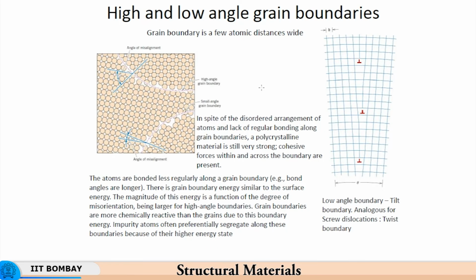The low angle grain boundary means that the two lattice orientations would have been the same if the misorientation had been absent. That slight misorientation is something that prevented the two lattice orientations from being identical, right? So the low angle grain boundaries indicate that two lattices would have been the same. They missed that opportunity by a whisker, by a very small degree of misorientation.